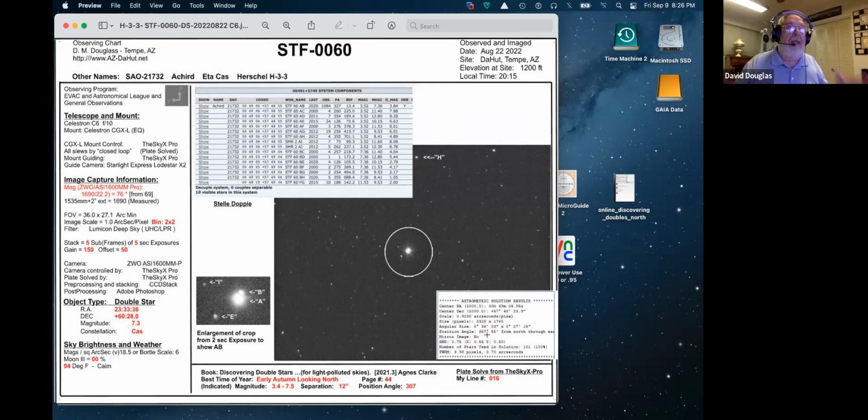So when I put that into the formula for the actual measurement, I've got to tell it I'm off by 3 degrees, and which way. That way it'll tell me the precise angle from the primary star to the selected one that I'm looking for.